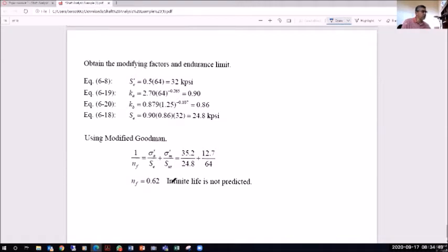And please note that we have to use the Goodman equation because we do have combined stresses. Not only do I have a sigma, but I also have a tau. This is a combined stress, and we have a static, or steady, torsional shear stress.